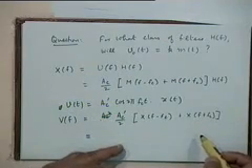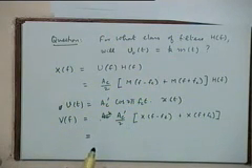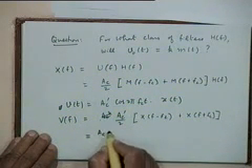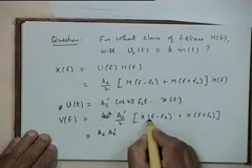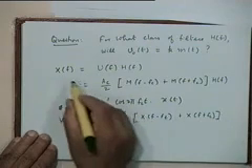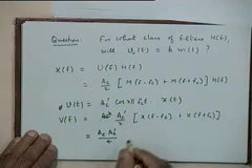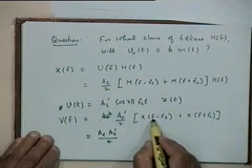These 4 terms that you will have here will contain 2 terms which correspond to the baseband component and 2 terms which correspond to the 2fc component. So let's first identify the baseband components. That will be Ac into Ac prime, right? Because you are substituting for X of f minus fc from here upon 4, right? What will be the baseband part? One component will come from